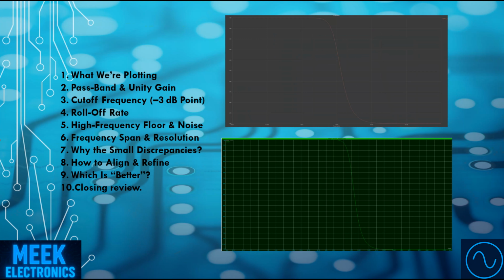6. Frequency span and resolution. Defaults differ. Proteus swept from 10 Hz up to around 10 MHz with a very fine grid. Altium went 10 Hz to around 100 MHz, but with fewer points per decade. More points give you a smoother curve, but take longer to simulate.